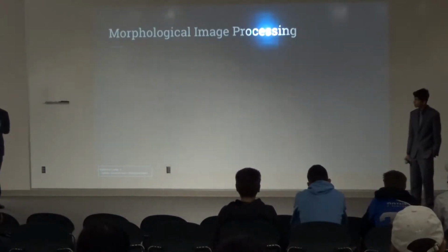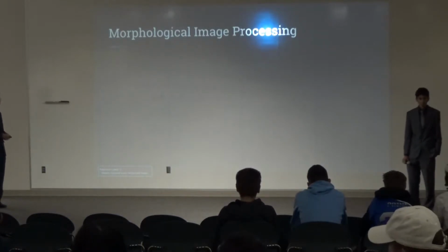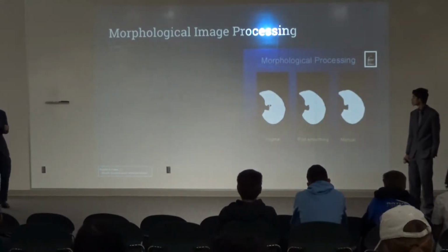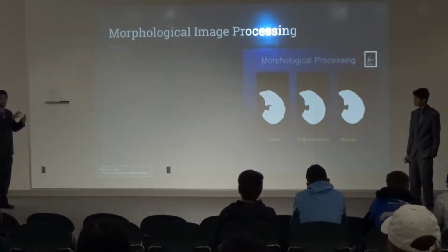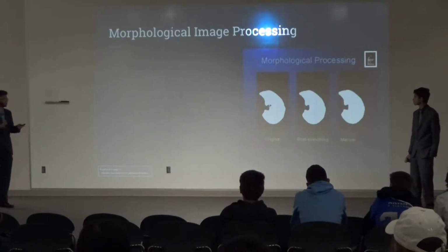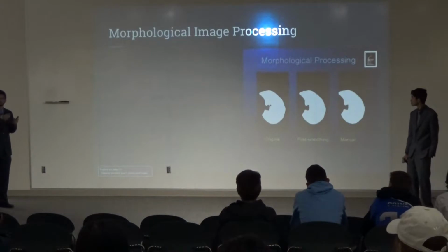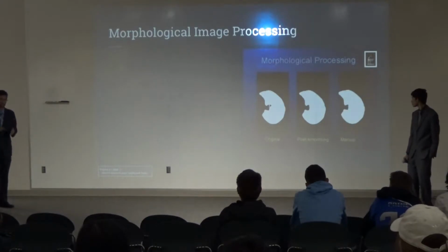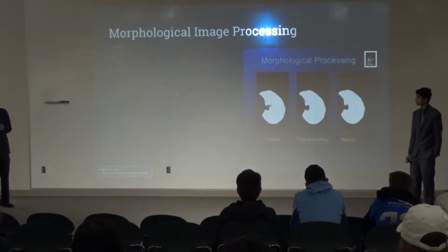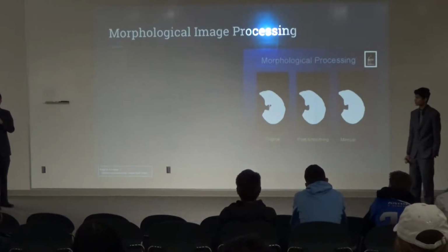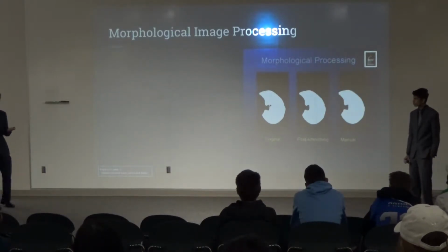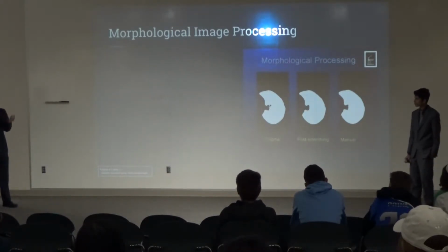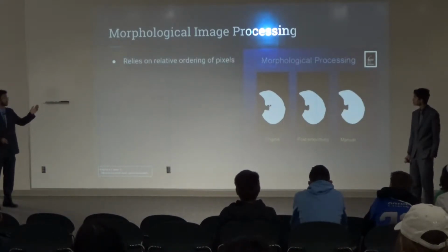Now we move on to the bulk of my project conceptually, which is morphological image processing. The main problem is that even though I managed to create a layer mask with the ball returned as white and the rest as black, there could still be instances where certain parts of the ball are not recognized by the Android camera. For example, if there was bad lighting or a part of the ball was discolored, that part would not fall under those HSV values and would be recognized as black. This could cause unnecessary holes in your ball or just not a clear image. That's where morphological processing comes in.